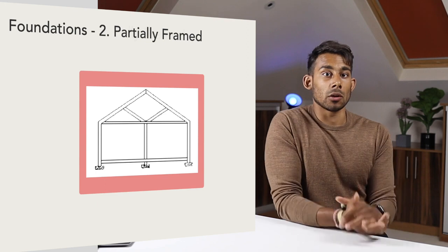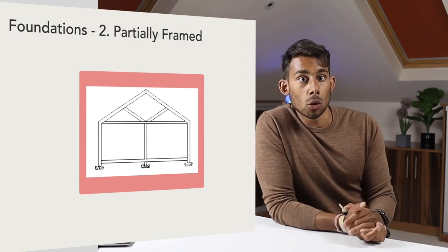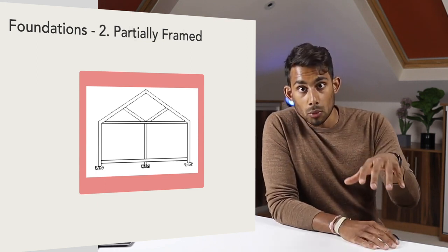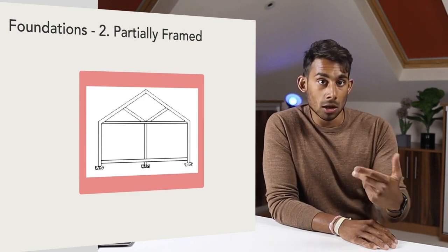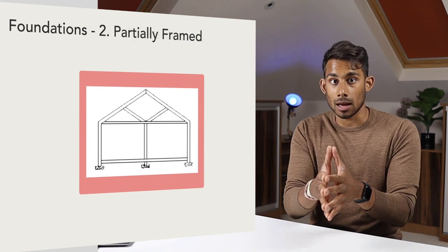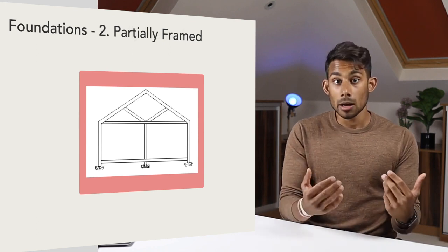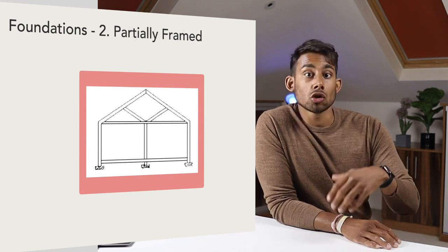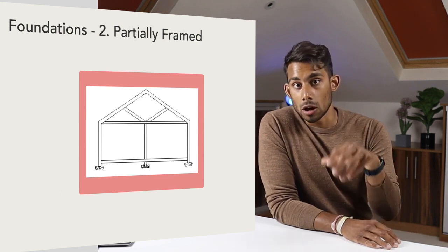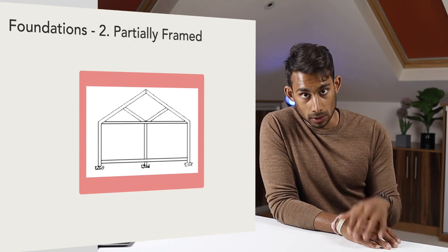Partially framed buildings of an old-fashioned type usually incorporate timber posts and beams, providing support for timber floors, or cast iron columns moulded for strength and appearance, and beams of iron and timber. In more recent buildings of this type, however, columns and beams are constructed of steel and are similar to those used in modern fully framed buildings.